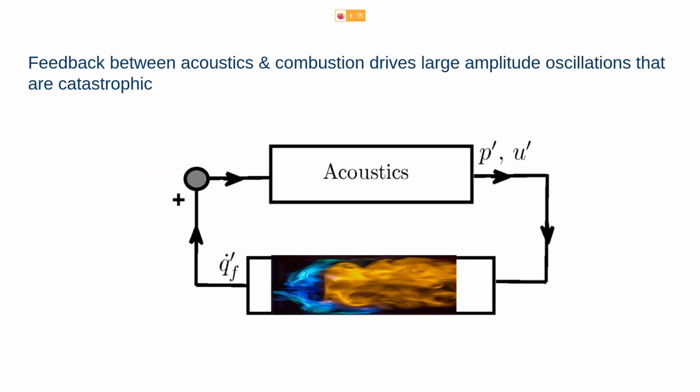In short, combustion instability means that in your closed confined chamber you have acoustics being set up inside your system. Acoustics in the sense that you have sound due to the flow or some other process, so you have pressure oscillations being created in your system. And in a closed chamber, these acoustics get energy from the combustion, which drives the system to very high amplitude oscillations.